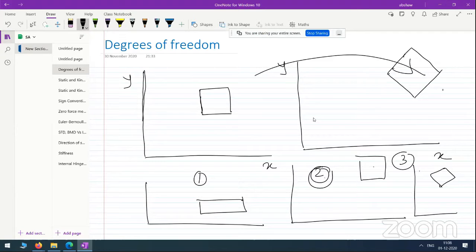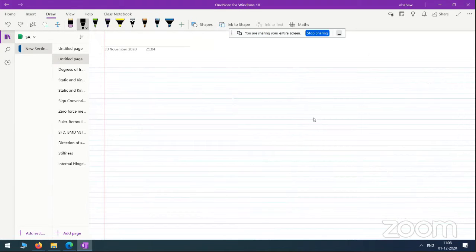Now, related to that, suppose you have a roller hinge support. Why do we provide support? Supports are provided to constrain some degrees of freedom. Depending on which degrees of freedom you constrain, you have to represent the free body diagram accordingly. You have different kinds of support depending on the different constraints against different degrees of freedom.